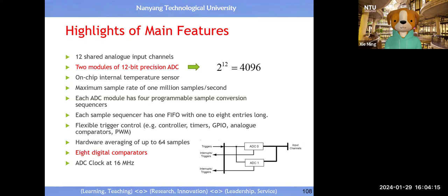So this chip has built-in support for each sensor. You can set the upper limit and lower limit built in for you. That creates a little bit of complication. You see, 8 is the comparator. You remember you have 8 jumping devices. Each jumping device will give you a pair of what they call comparators for you to set the upper limit, lower limit.